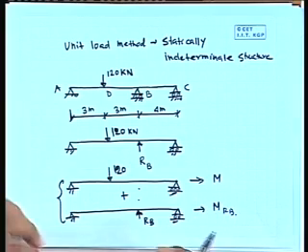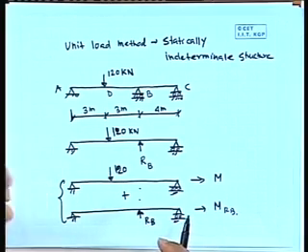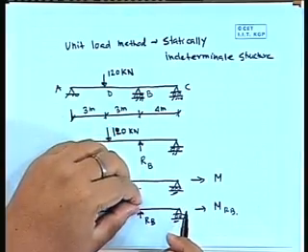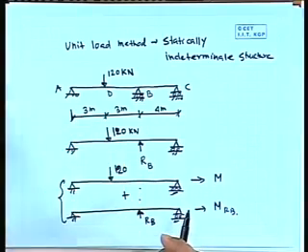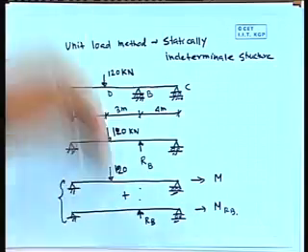Okay. So if we put RB in the reverse manner, here the problem is simple, we are taking RB intelligently in the upper direction. So this value and this value will automatically be opposite. Numerically we can put the value, but if we follow mechanically, we will put all the load in a downward direction.